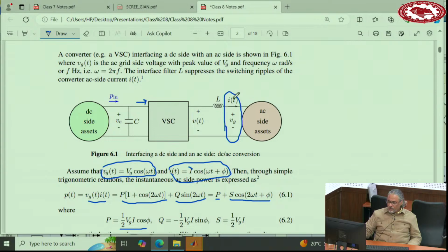That means all the AC power here must be supplied by this capacitor in order to make the balance of power, right? This is kind of a worst case scenario, saying that this power is perfectly DC and this is DC plus AC. So DC comes from this one and AC comes from the capacitor.